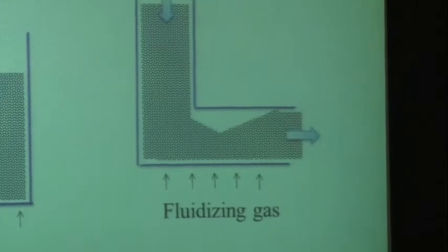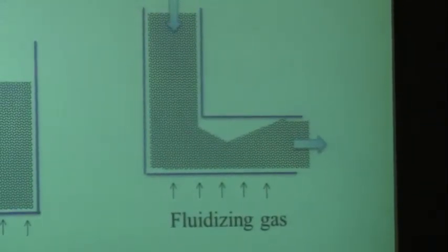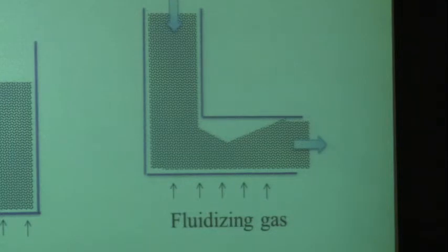If you don't add any fluidization gas, what happens? Stops dead when you don't fluidize it, right? Because solids don't flow like a fluid. So actually, to control the flow rate, you just control how much fluidization gas you put in that part, and that controls how much is going around that loop. If you don't put any, it will stop. By the way, if you do this in the lab and you stop it, well, just don't do that. We can talk later why you don't want to do that, all right?